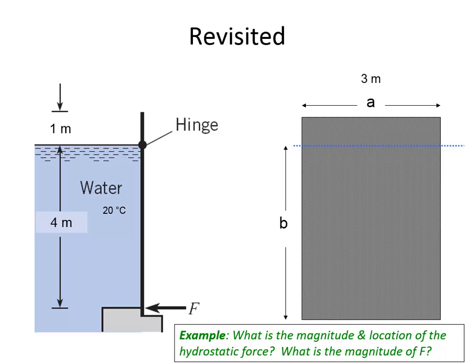And one thing to try and visualize is what's the pressure distribution along that plate. Now, here's a plate, the pressure starts at 0 at the top of the plate, and the pressure is increasing at a rate equal to the unit weight of the fluid. So this is water, and the pressure is going up as we go down through the fluid.